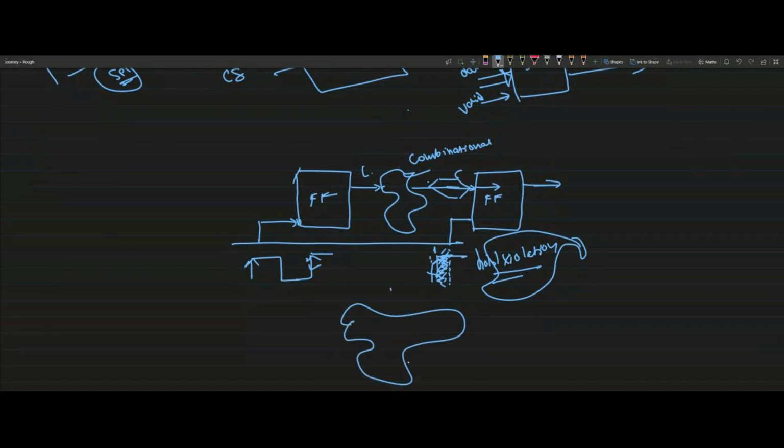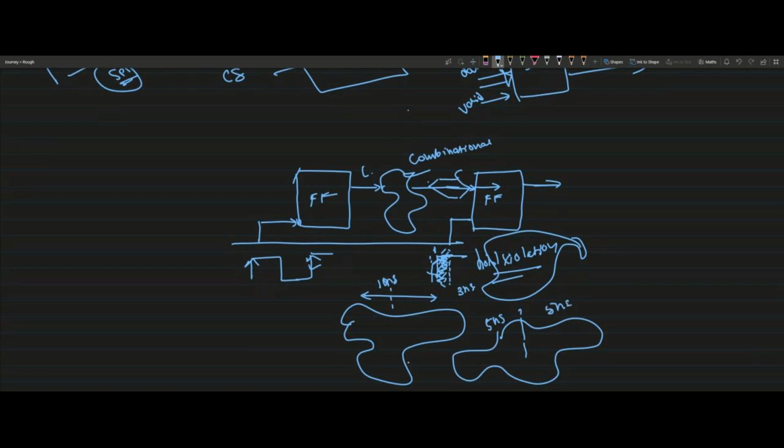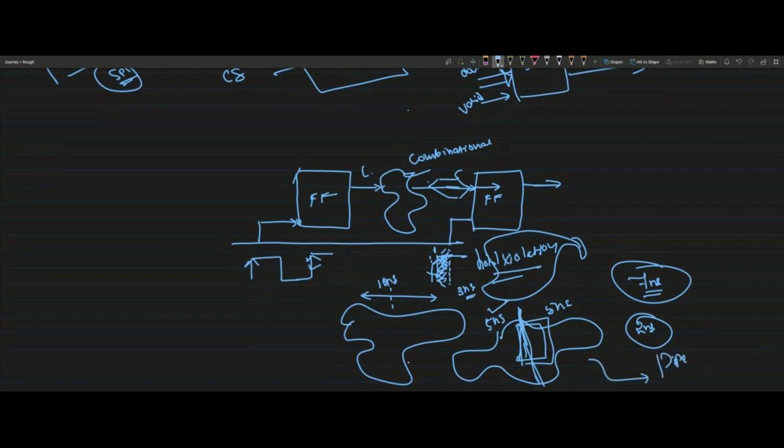So for example, this path is some 10 nanoseconds, and here you have a setup violation of 3 nanoseconds. Then what I can do is split this into 5 nanoseconds and 5 nanoseconds. That is where I put a flip-flop in between. Previously, since it was reaching at 10 nanoseconds, there was a 3 nanosecond violation; 7 nanoseconds is still allowed, right? But here, since I have 5 nanoseconds, I still have 2 nanoseconds of time. That is where I avoid this setup violation. Adding this flip-flop, we usually call it a pipelining mechanism. Pipelining is the mechanism where I add flip-flops and avoid these delays and violations.